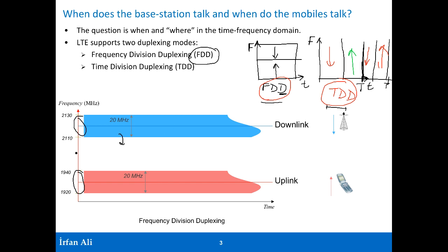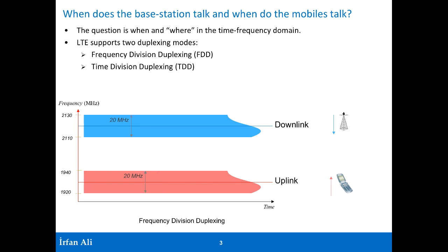And so the uplink and the downlink bands are separated by some interband frequencies, and you end up in LTE with the maximum, as we had covered in the previous lectures, of 20 megahertz in the downlink, and you have a paired spectrum of 20 megahertz in the uplink. The uplink is always at a lower frequency than the downlink, and you can think about it and see why. It's a pretty simple explanation.